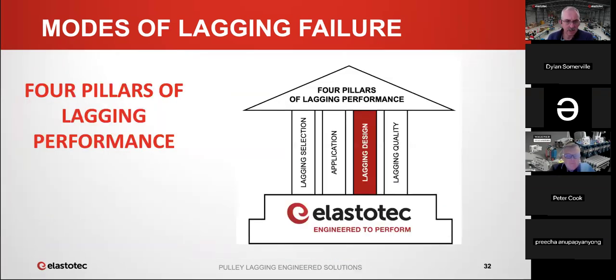We'll next look at lagging design. The lagging design includes things like the bonding system that is used for the lagging. It also includes the shape and size of the lagging pattern, the amount of ceramic tile coverage, and also the material that's selected. You know, what sort of flexibility the material has, what sort of coefficient of friction, abrasion resistance, etc. They're all things that go into the design of the lagging.